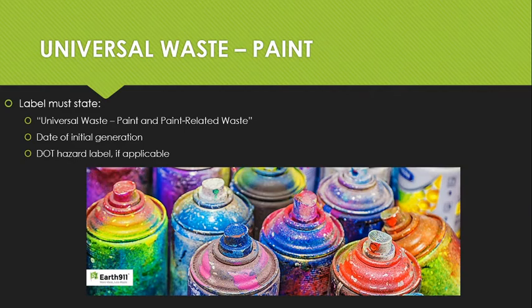So for universal waste, it must say paint and paint-related waste. So once again, a very specific phrasing. Has to have the date of initial generation, and it really should have a DOT hazard label. So you may have a universal paint waste sticker on that drum of aerosols, but you're also going to need a flammable gas sticker on there. So like I said, just because it's not hazardous waste doesn't mean it's not still considered hazardous in DOT rules and regulations.